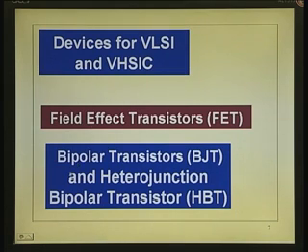Other devices which are used in circuits like emitter coupled logic or some linear circuits are the bipolar transistors. And when you have the ability to grow heterojunctions with 3-5 compound semiconductors with ternaries, you can have the heterojunction bipolar transistor, HBT, very popular in 3-5 semiconductors, not merely 3-5, 4-4. Silicon germanium with silicon, you make HBT.